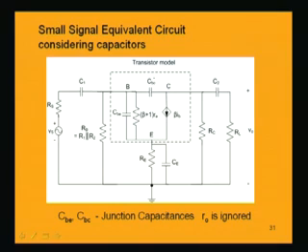Now, the effective capacitances will be these two, because these capacitances are no longer open circuit, their capacitive reactances are smaller, so that a part of the base current is shunted out through these two capacitances. That is, out of the current which is coming into this point, one part will be shunted out through this capacitance, another part will be shunted out through this capacitance CBC, and the rest will be only flowing through the resistance (beta plus 1) Re.